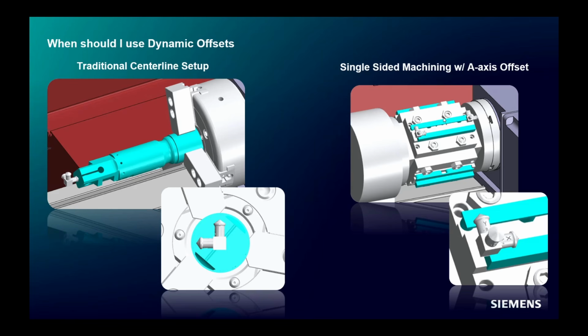So once the rotary axis has spun into position, setting what we would call our surface normal, so I'm either like A0, A90, A180, there's no extra rotary motion. So in a case like that, I can handle the orientation of the part right at the fixture offset level. And I don't need to worry about where the center line of the part is because I'm not moving it around. So just because I'm on a tombstone, don't think you have to go dynamic fixture offset. Probably not a huge benefit there.